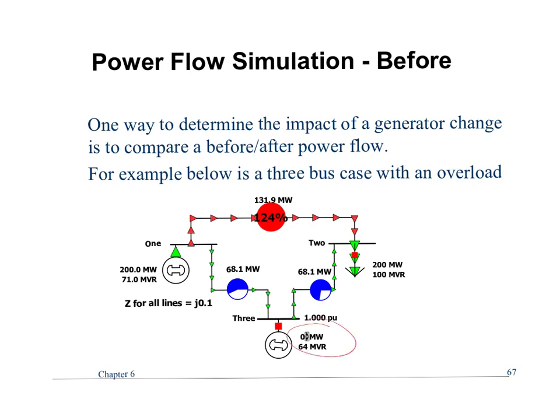And if I'm trying to be a generator bus maintaining 0 power here, and I've got my load here, and this is 1 per unit, this is 1 per unit, you can see that I've got all the real power going here, and my reactive power 71 and 100. So I've got more I squared Z or X losses. So this line is at 124% of capacity.